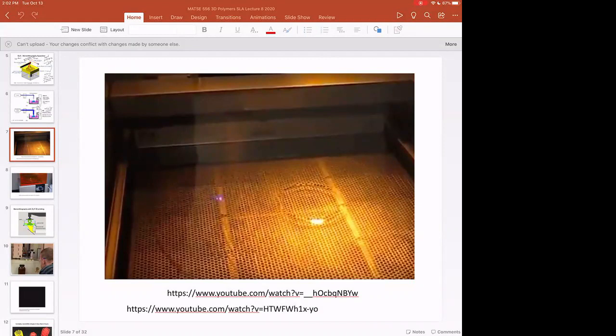And so this chemical reaction bonding basically causes an increase in molecular weight. And in general, if we have the right chemistry, when we increase molecular weight from monomers and oligomers to polymers, we get this liquid to solid transition. And that can happen extremely quickly, within 10 or even 50 milliseconds.